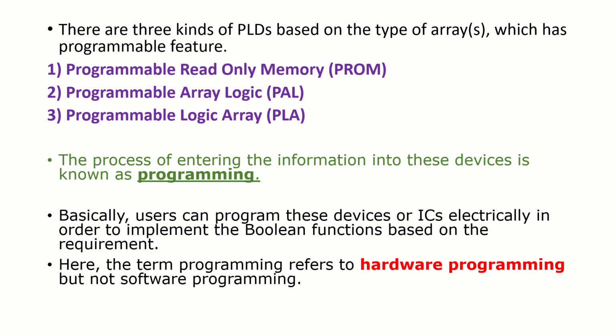Now, there are three kinds of PLDs. First is PROM, which stands for Programmable Read-Only Memory, PAL, that is Programmable Array Logic, and PLA, that is Programmable Logic Array. The process of entering the information into these devices is known as programming. Now, programming doesn't mean that you'll have to use a programming language like C, Java, Python, etc. Here in digital electronics, programming means we are talking about hardware programming and not software programming.